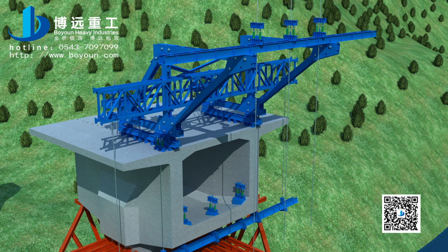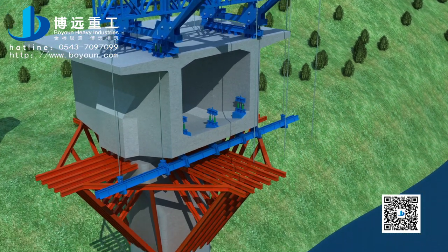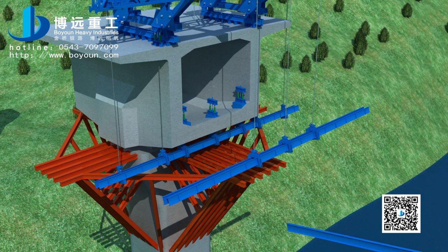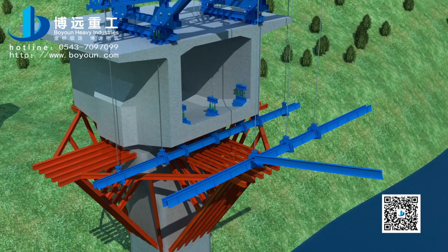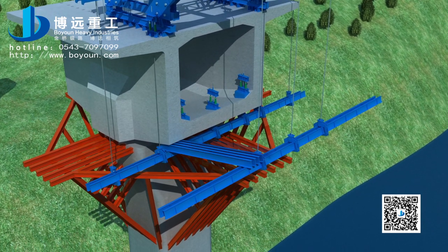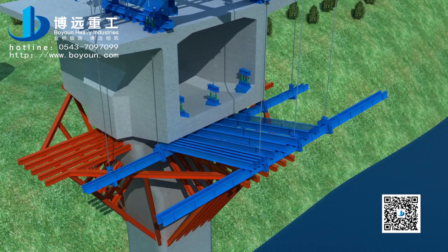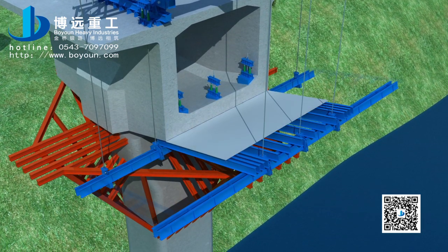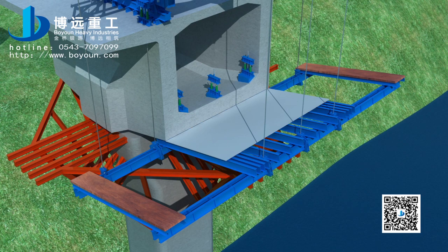Lift the front joist and fix it on the front upper cross girder through hanging system. Install the bottom longitudinal girder according to space, specification, and route number of forming traveler installation drawing to weld on the front and rear joist. Then, install bottom framework and walking platform.